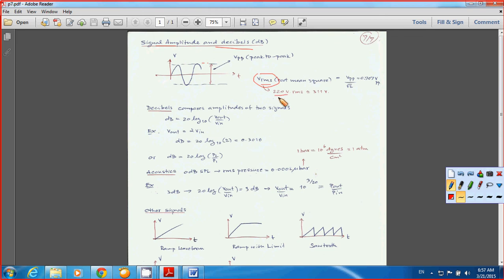Just like when you use the voltage source of 220 volt for electric appliances in our house, we usually talk about the voltage in VRMS. But if you want to compare to peak, you need to multiply 220 volt by square root 2, and it gives you 311 volt peak.